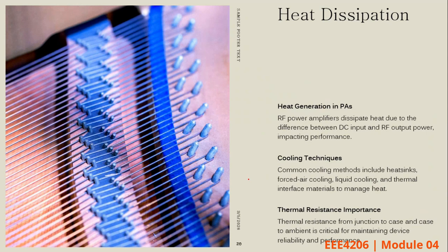So remember that any power that is not converted into RF output becomes what you call heat inside the transistor. And if this heat is not properly managed, the device temperature rises, which can degrade performance, and eventually it causes failure. So engineers use several cooling techniques, and these include heat sinks, forced air cooling, and sometimes liquid cooling in high power systems. Yeah, I mentioned this one.